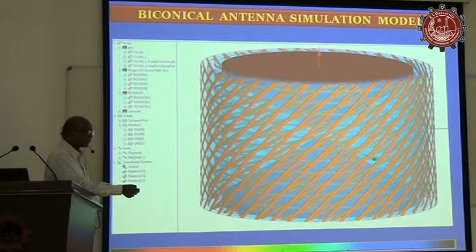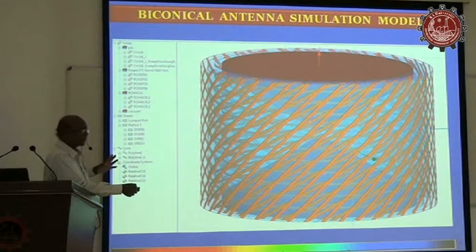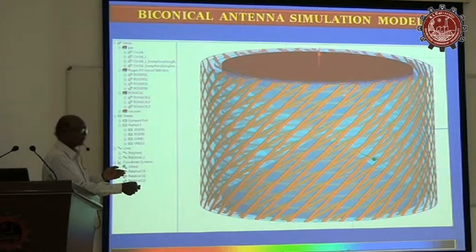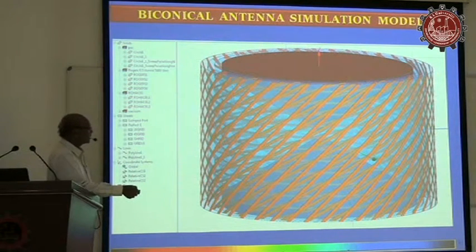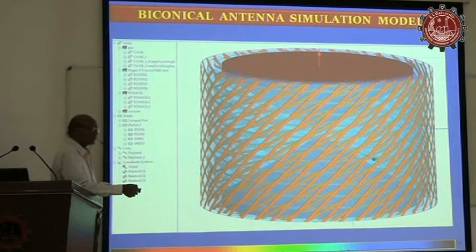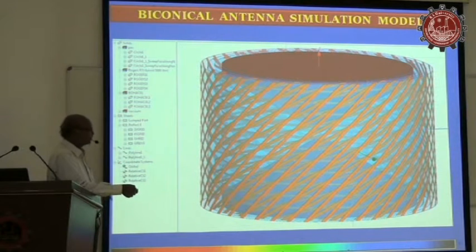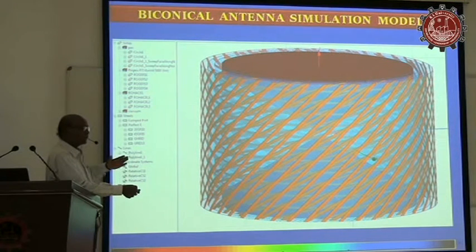To make it slant polarized, we have used a wire grid polarizer. Normally we use a 3 or 5 layer polarizer. Each polarizer grid is at a different angle, suppose if you are using 3 grids, 0, 15, 45, because at the output we want 45 degrees and the incoming is vertical. Another basic principle in designing the wire grid polarizer is that the first grid should always be perpendicular to the incoming wave, because it is vertically polarized. The first grid should be horizontal, then the next will be 15 degrees, then 30 degrees, 45 degrees.